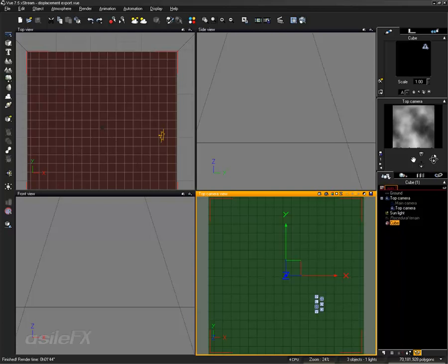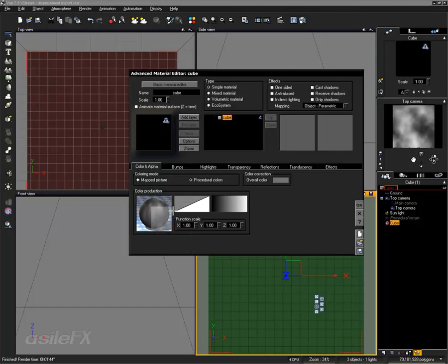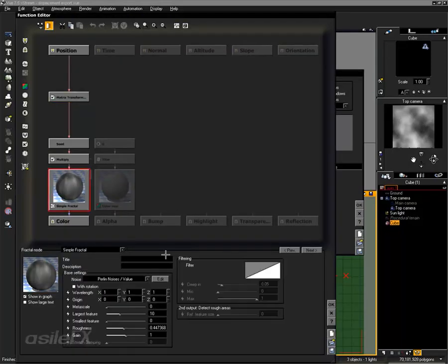If you find that the image you create directly from the procedural, having the entire height, doesn't have enough detail for a normal map or bump map, depending on how it is you're using the normal map, for something that's tangent based, you would want a little more detail locally for each individual normal. What you can do is modify the fractal a little bit more to decrease the gain amount.